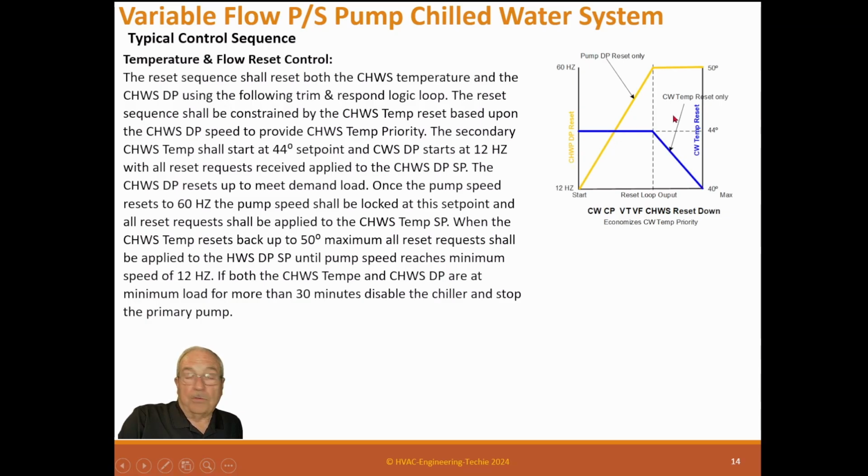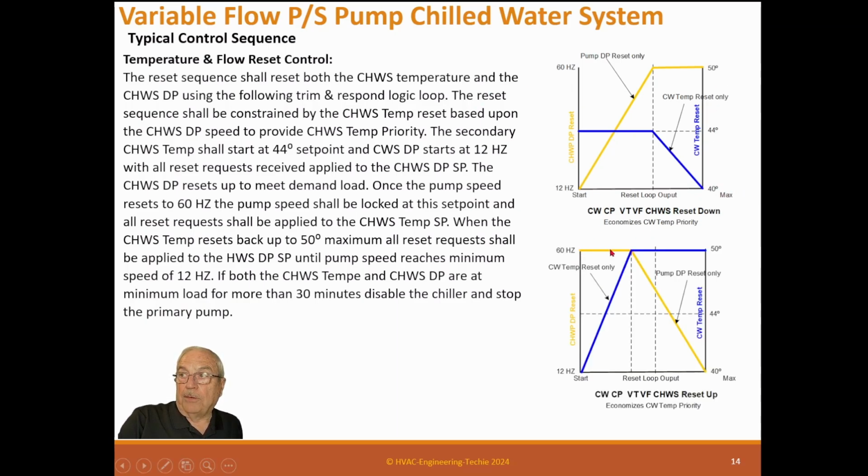So basically what we're doing is we're trying to cool the building with as little water as possible. So we're increasing the pump because we've got 44 degree water. We're trying to cool everything in 44 degree water. Now, if it won't do it, then we'll start lowering the temperature, which increases the energy usage of the building. We're trying not to do that. So as it goes to here, so now when we get to this point and we go down, our pump's at 60 hertz, and so we get to this point, this is down at 40 degrees cold.